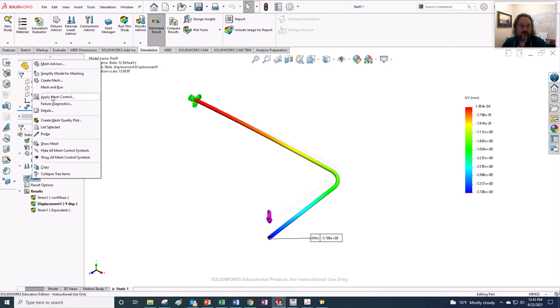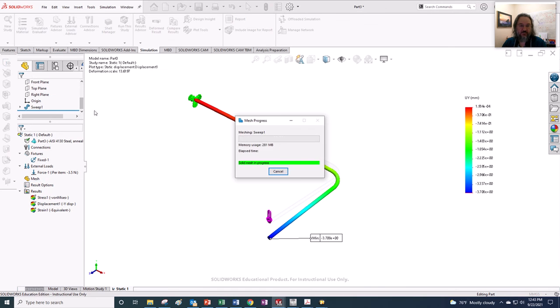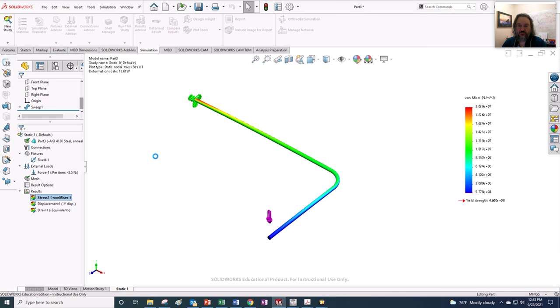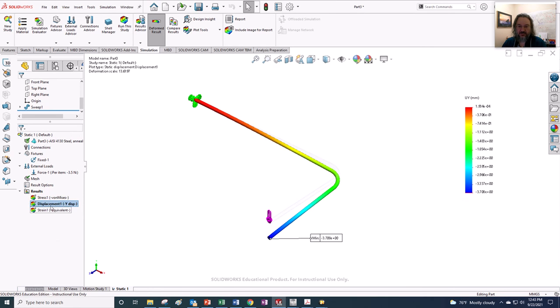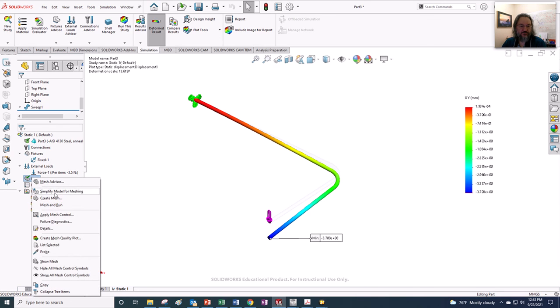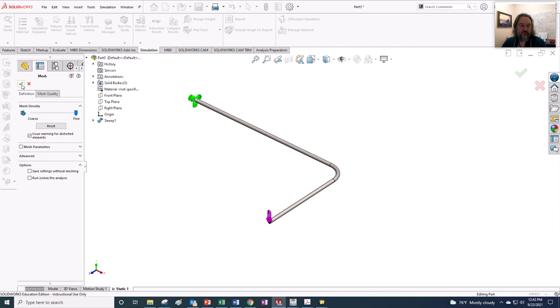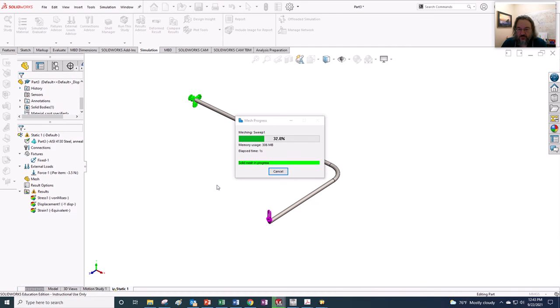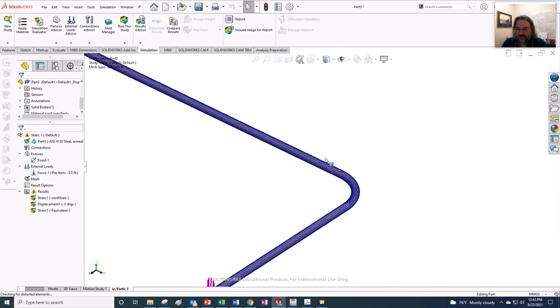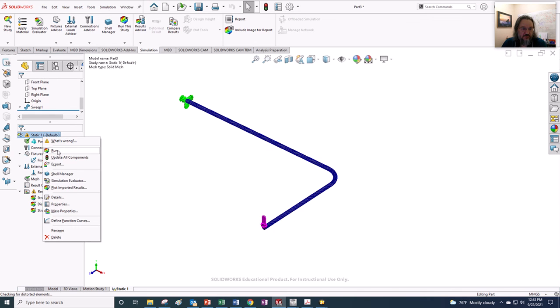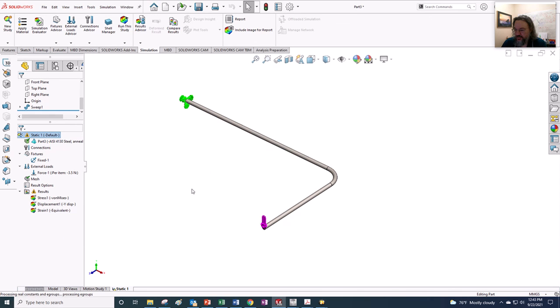What would happen if we were to create a mesh and run? So I'm going to hit the mesh and run thing here, and it took the default right in there. I hit that show again. I got to go. So I'm going to create a mesh, and what would happen if I just ramp it up all the way to the side right there? And we're going to get really tiny mesh right there. The elements got much smaller. I'll hit run. Let's see if it takes a very long time to do.